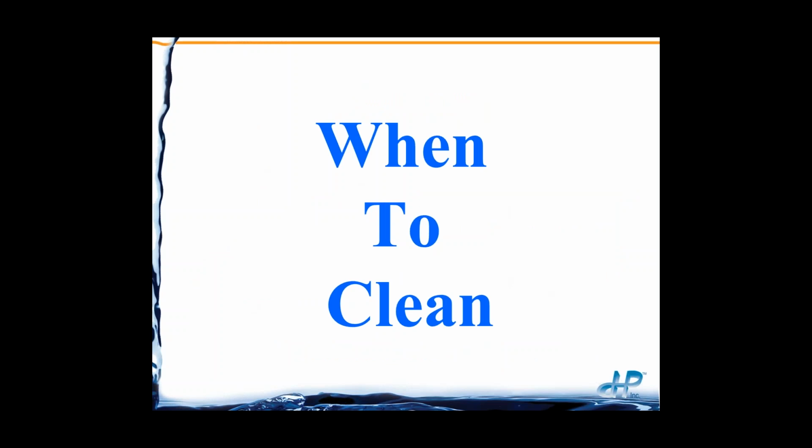All right, so we've talked basically about how we scale and foul. We scale due to concentration, and we inject scale inhibitors to keep us from scaling, or we have water softeners up front to keep us from scaling.